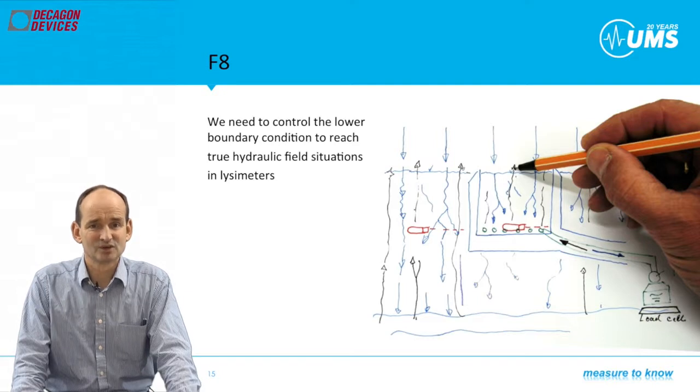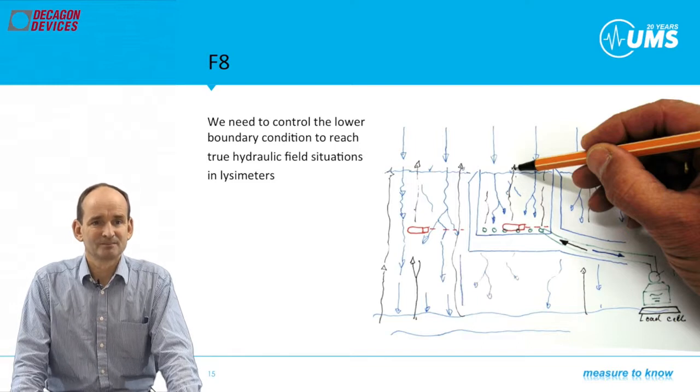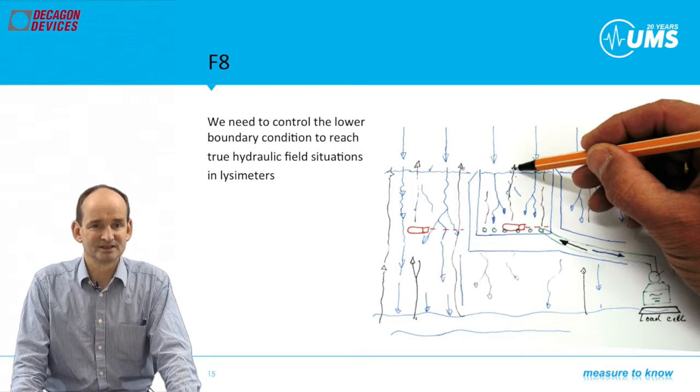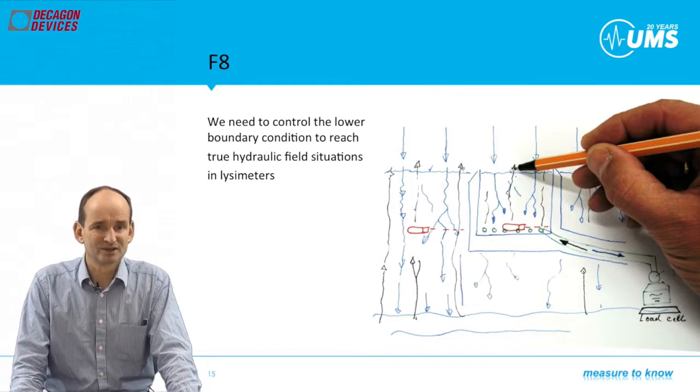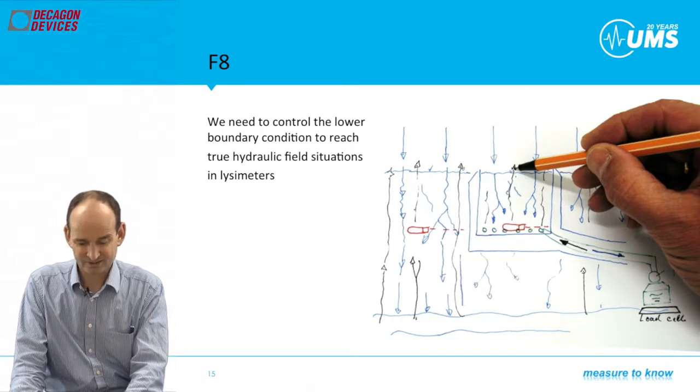If the barrel is full, we release a defined amount of water back into the field below the lysimeter. With this, the natural flux situation got only a bypass, but the field balance is remaining. Sure, for measuring the drainage water amount, we measure the drainage tank with a balance too. The technical components and details are part of the next chapter, Technique.